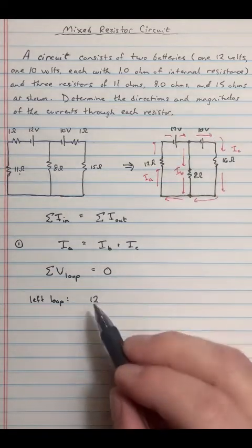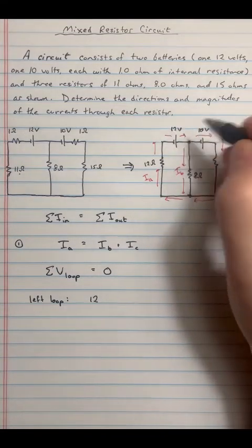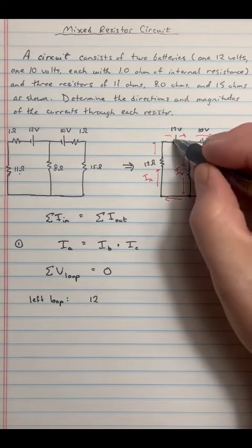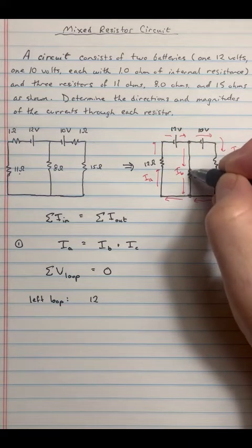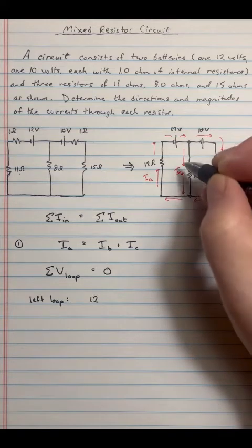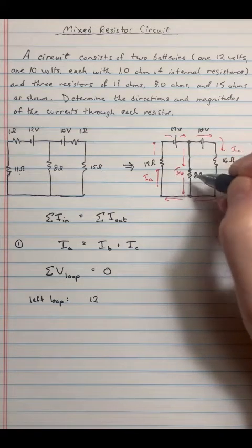But with that in mind, 12 volts. So I pick up 12 volts. That's the language you use. I go in this left-hand loop. That means I go down this way. I hit this resistor. There's 8 ohms multiplied by the current, unknown current IB.